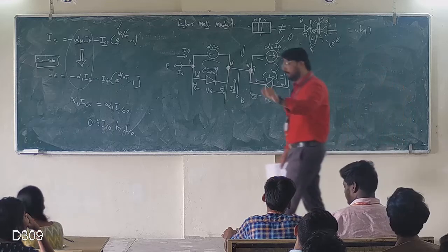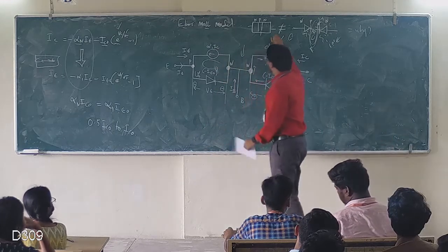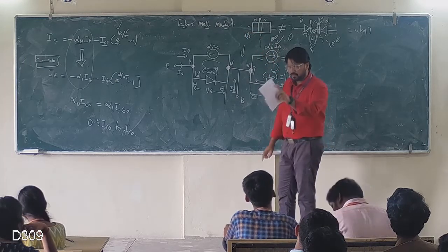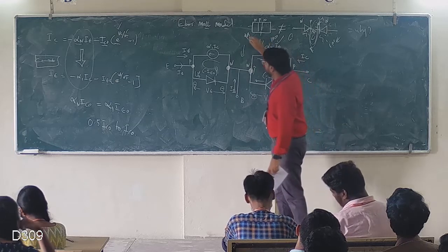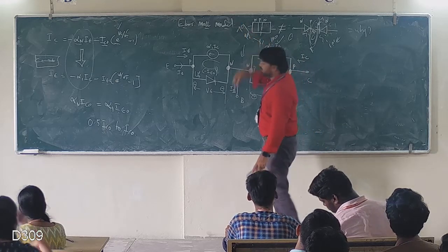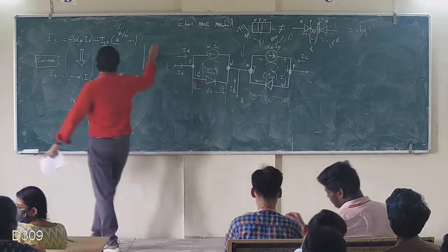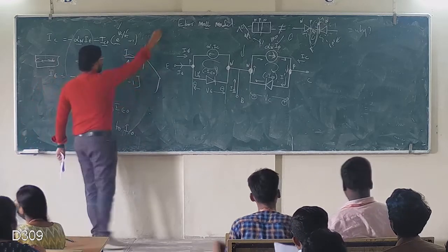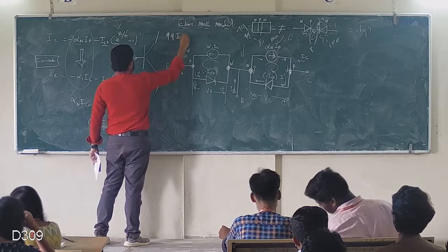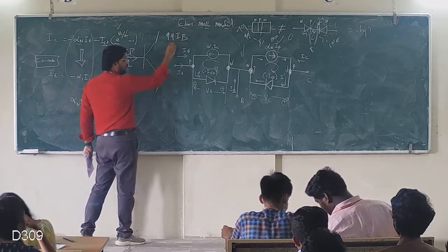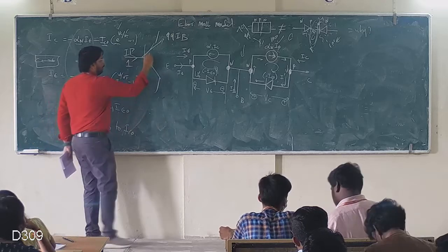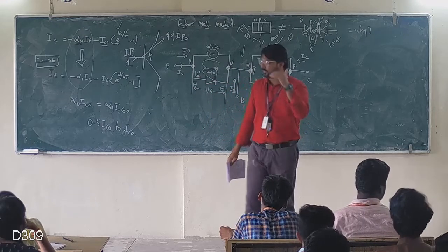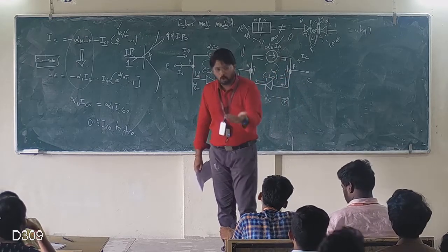Whereas what is a transistor? It has recombination. What happens? 100 electrons may start, 99 reach the collector, and one is lost in the base. Which means if I connect 1% as input, I could have an amplification factor of 99 times. You got the point? What is a transistor? Transferring a signal from one port to another port. What is the base current? Base current is equal to 1. What is the collector current? It is 99 times IB. What is this 99? Beta, the amplification factor. So why is the amplification factor of a transistor very high? Because recombination is almost 1%.